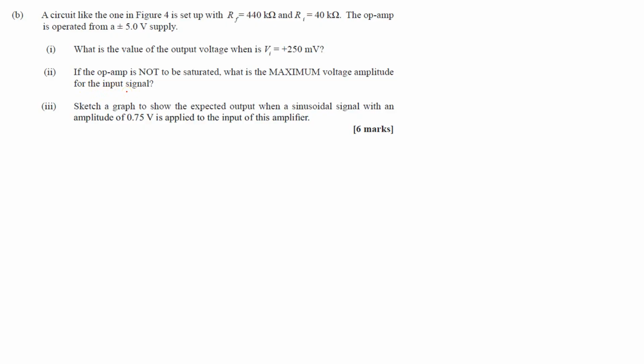This question is so tricky because what you must also understand, guys, is that the point when the amplifier reaches its maximum output, which is 5, is the point when the operational amplifier will not saturate, and also the point at which saturation will take place. So it's a very tricky thing. You're on the borderline of saturation and not saturation. That's the best way to look at it.